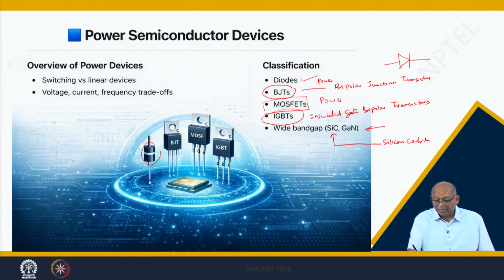These others are just silicon devices, only silicon, not germanium, but this is silicon carbide bonded together, which increases the breakdown voltage, makes it faster, and gives better thermal conduction. This is why it is nowadays very much preferred. These power MOSFETs etc. are actually designed. You can say SiC diodes, SiC MOSFETs. These are now becoming very popular.